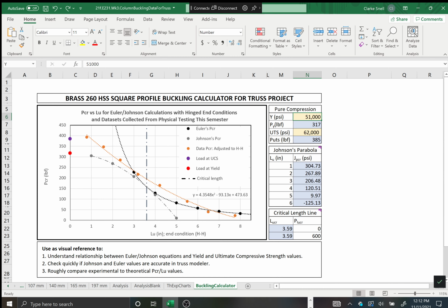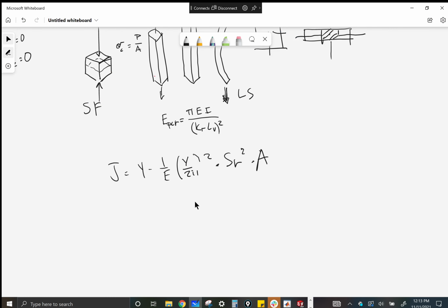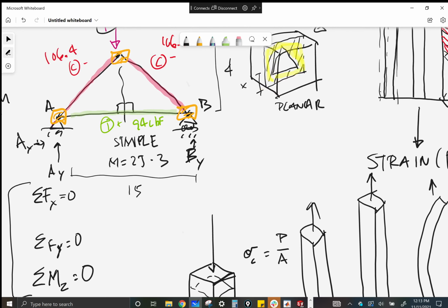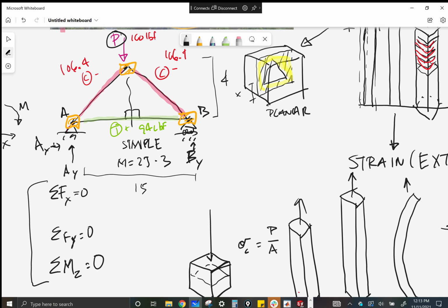So okay, let me look at my notes. See if there's any terms, load ratio. Okay, I'm sorry this is a little bombastic, but this is just stream of consciousness. I'm going to call these load ratios, and do people understand why? Yeah? Not actually load, it's the ratio to any theoretical load that's placed on it. Yeah, it's the percentage of the load in the truss that a given member will take. And so it's relative between the different members.